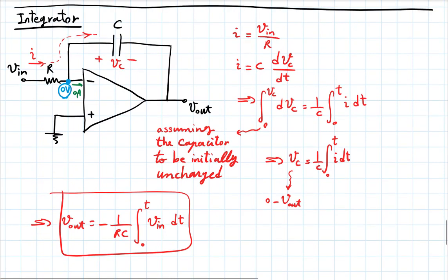Now imagine, by the way, that you build a few functionalities like this with op-amps, but then you want to make the whole thing into an integrated circuit. So instead of actually buying op-amps to put on a breadboard, you'll say, no, I will just include the circuitry of the op-amps on my chip. So all of a sudden, let's say you had designed something that had 5 op-amps in it. Now you replace each of those op-amps with their circuitry that might have 20, 30, 50 transistors, and you lay it out on a chip.